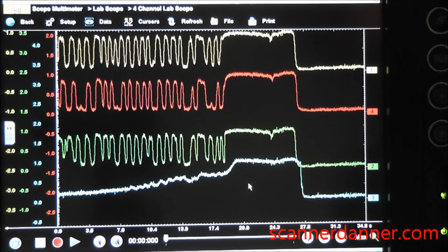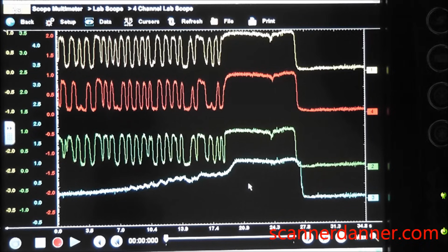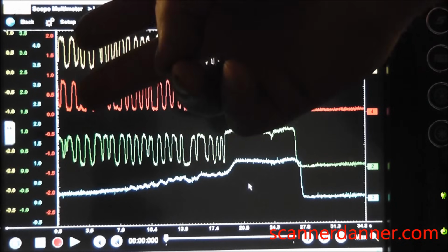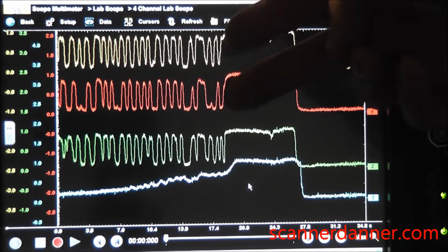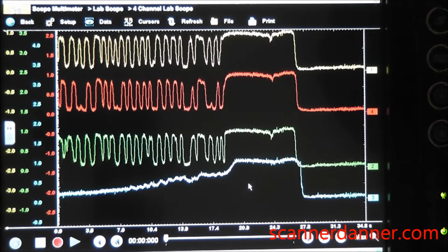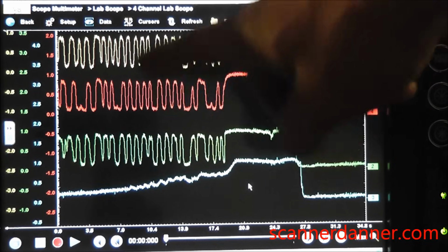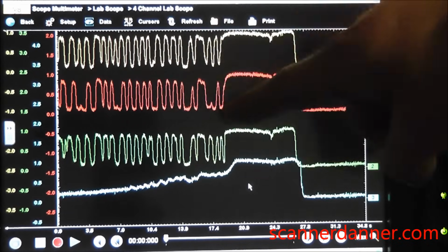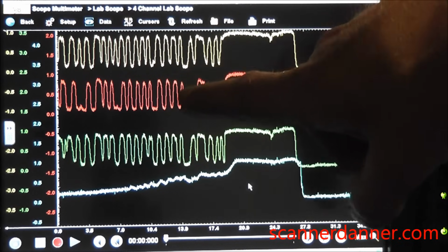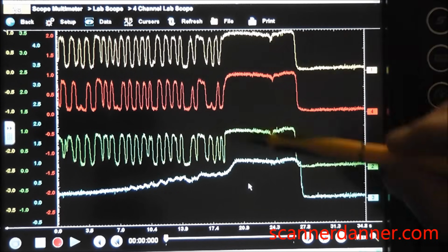And remember, we have a cat code on bank 1 only, no code on bank 2. And really looking at just the upstream and downstream O2 signals as the scan data showed us, this is really enough info here to condemn the cat. We ran it for a long time. We should never see a hot cat with the same frequency and amplitude as an upstream. So the downstream sensor, the cat monitoring sensor, we don't want to see the same frequency and amplitude as the upstream. Definitely a bad cat for these two.